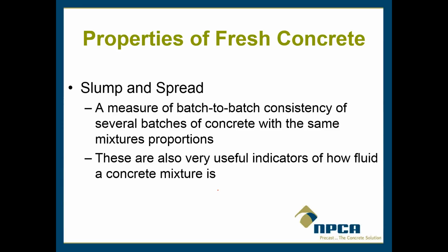So yes, that's really good actually. Slump tests are done to measure the consistency. Two different types of consistency actually. The consistency of the concrete itself, the flowability of the concrete, the ability for fresh concrete to flow, and the consistency between batches. It is not a measure of how much water is put in the mix. It's not a measure of the water to cement ratio, and it's not an indicator of the concrete strength. So those are really common misconceptions.